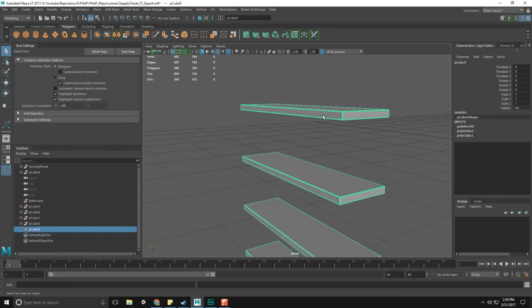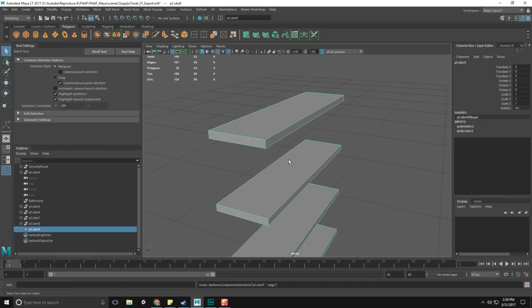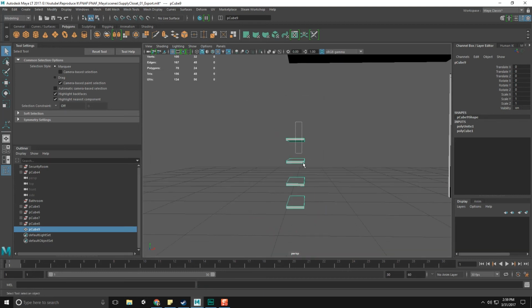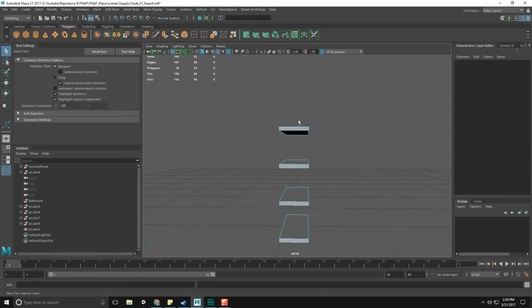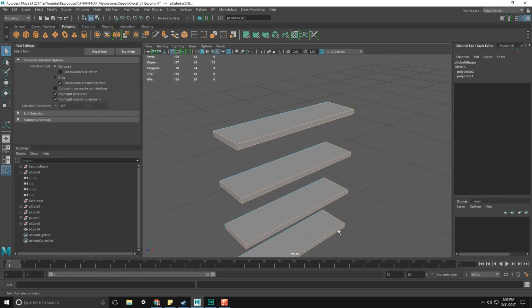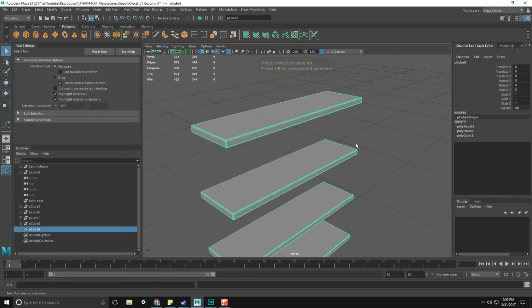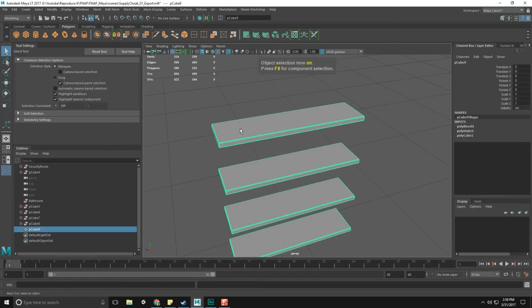The backs aren't important. We could technically not bevel that part of it if we want to. It's probably a good idea, actually. I don't know what my poly count's getting up to at this point. Edges, grab all of you, and let's just bevel them. Bevel, segments 2, 3, and fractional amount a little bit lower. There we are. Good for me.